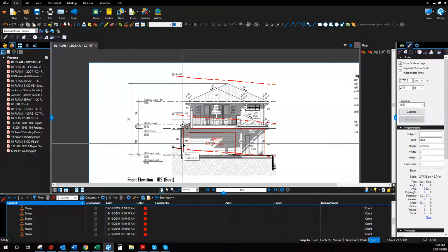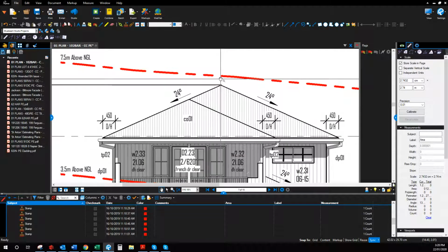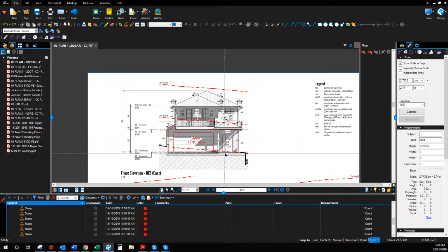So if you're ever sales estimating a job, and it's marked as very close or above, you'll know that we've got an issue and there'll be extra costs there for the client and there'll be delays. Okay. So basically, if you're very close, you need to get a height certificate from the surveyor. They'll come to site and double check these levels before the guys actually start building the house.